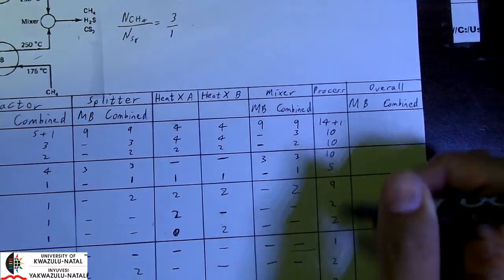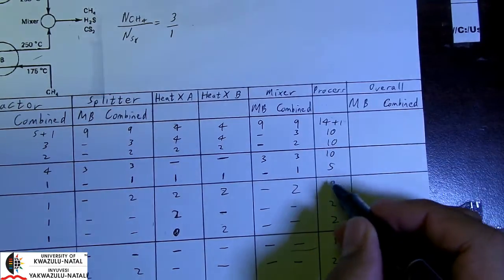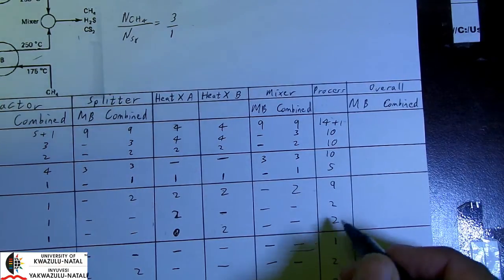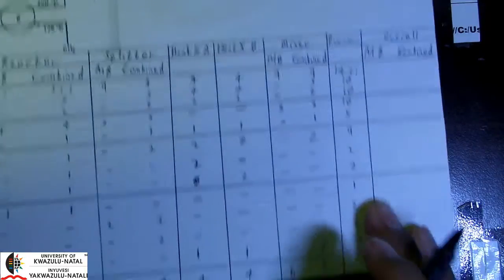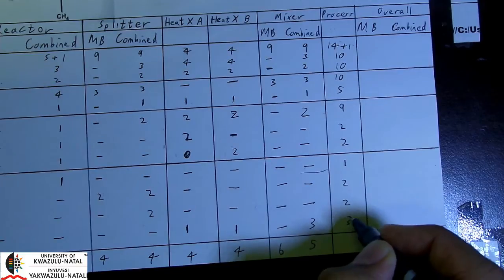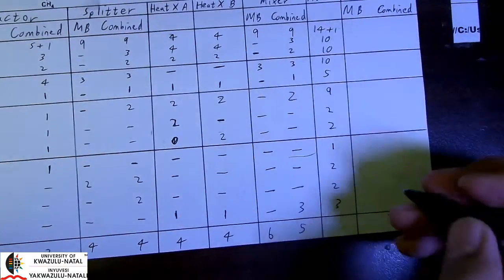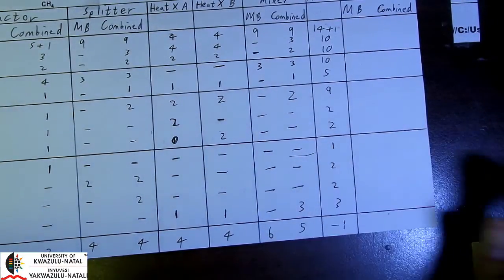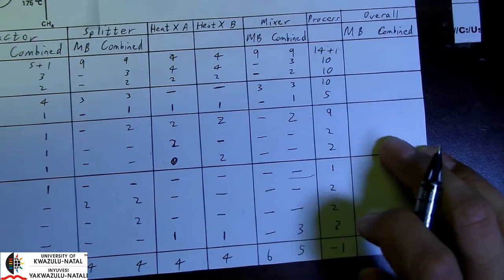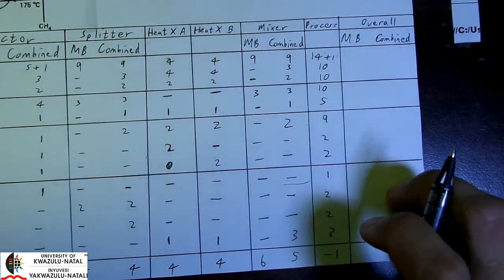Let's count our other specifications. So I have 10 plus 5, that's 15, plus 9 is 24, 25, 26, 27, 28, 29, 30, 31, 32, 33, 36. Okay, so my process is actually over specified. 35 minus 36 is minus 1. Okay, so we do ultimately have more than enough information to actually solve this problem. Perhaps we have extra information and we may end up with some inconsistencies.